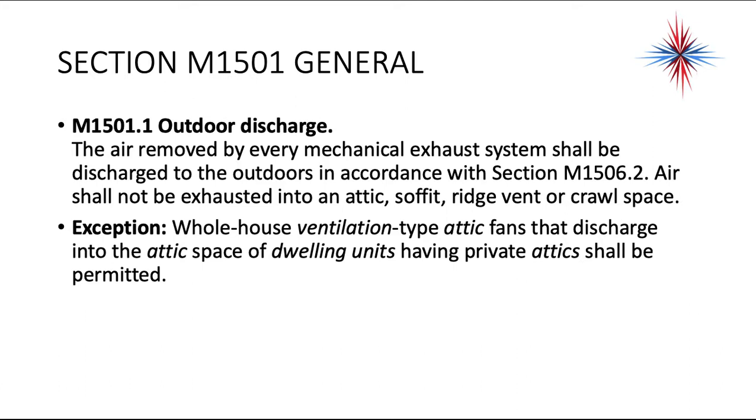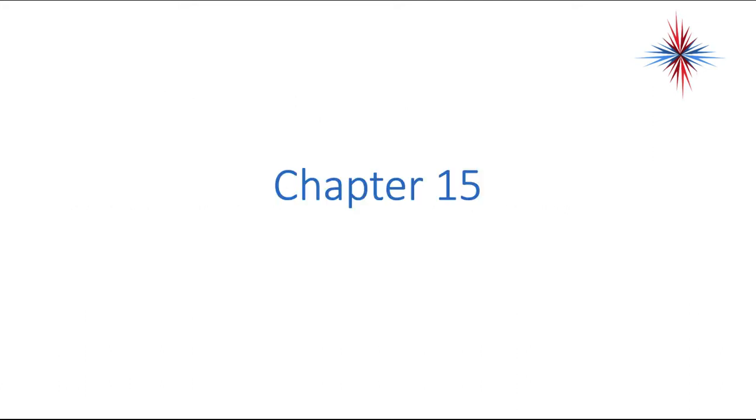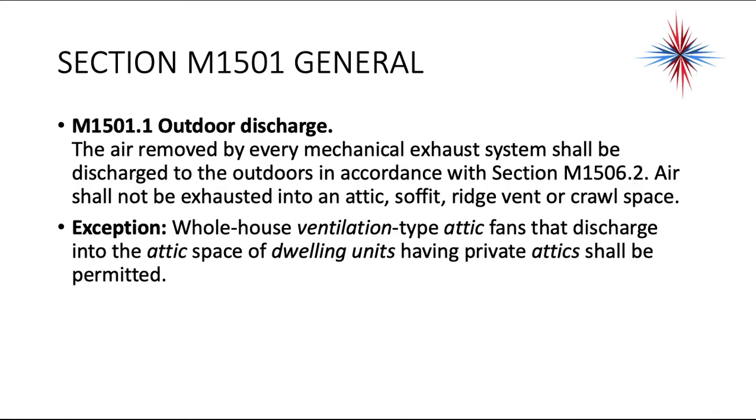Chapter 1501 starts with, it's basically talking about ventilation and exhaust. So it's saying outdoor discharge. Air removed from every mechanical exhaust system shall be discharged to the outdoors in accordance with 1506.2. Air shall not be exhausted into an attic, soffit, ridge vent, or crawl space.